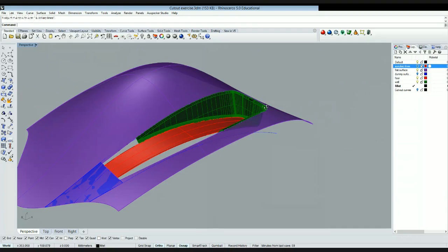Okay, so now we have to close these two rectangular gaps in order to finish our cutout. So there are two options here. The first thing that comes into our mind is to create again a two-rail sweep using this S edge here and sweep it along the floor and along our surface. This is one option, and I'm gonna do it from this side. And I'm gonna use this command curve from objects, duplicate edge, and I will select these two little edges and press enter. And now I have created two lines out of my edge.